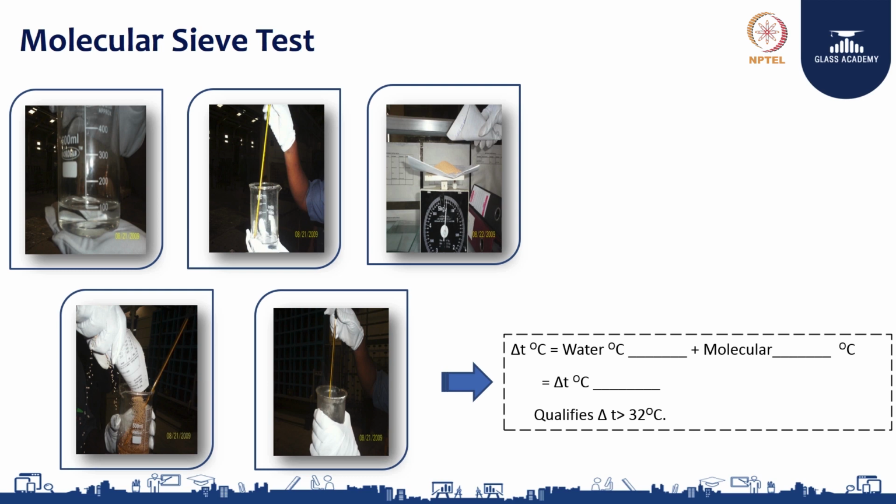You will have to do this test every time. If it is not handled properly, or if the sieve has absorbed water, hydrocarbons or pre-nitrogen, you will not be able to get this value. So every time, please ensure you do the molecular sieve test.